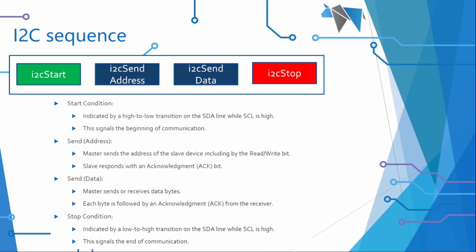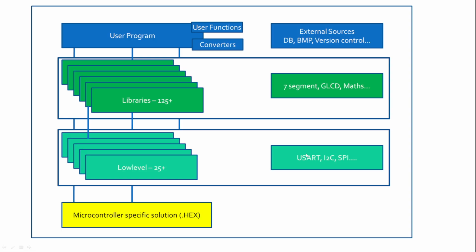We're going to see this I2C protocol of start, an address, sending data, and a stop, all happening in the background because it's within the library. So we've seen how this worked in discovery. We sent out a start, we sent out an address, and if it responded with some data, then we knew it was there. But this time we're going to send real data out.